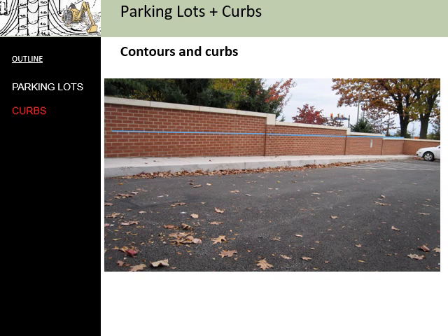To make this more obvious, we've added a blue line here running along the wall, and it's running with the bricks, and it represents one line of even elevation. So you can imagine a contour line is going to run along that wall at even elevation, basically running along the same line of bricks horizontally all the way along that wall.